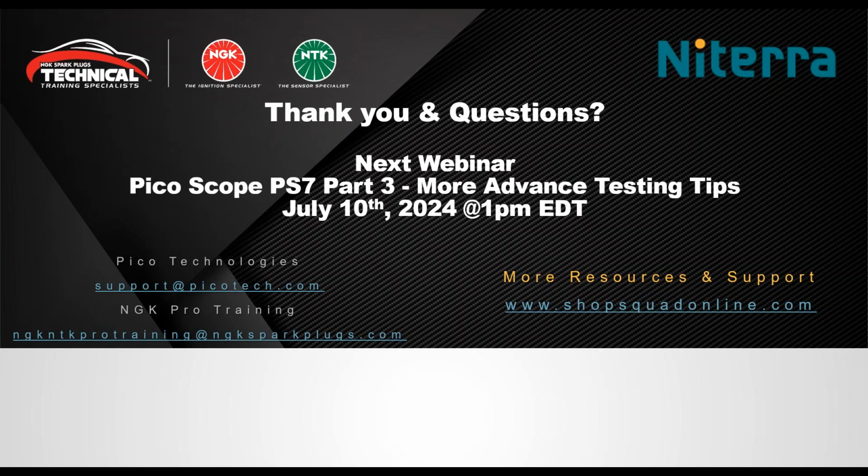I'll only filter when I think I need to, but then I'll also step back and think, why am I filtering this? Why does this have to be filtered so much? Is this normal or not? Maybe that's where the waveform library helps. I think you'll find that most technicians will filter everything. They'll over filter. I find people over filter more than they under filter. They over filter and send me stuff that I can't even analyze because it's over filtered. Fortunately, if it's DSP, I can just shut it off and look at what we're looking at.